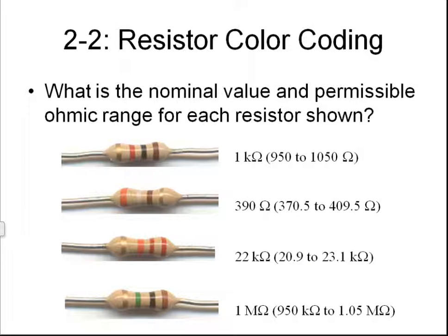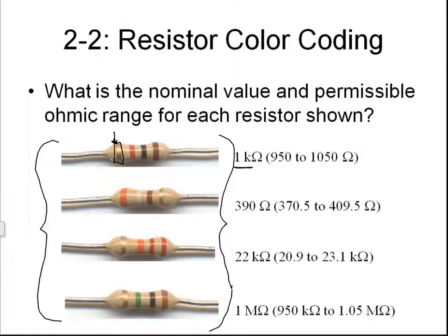All right, and here's another set of color code ranges. By the way, most of what I'm presenting here can be found in your Lesson 1 Chapter 2 PowerPoint slides, so download them and go ahead and review them. And you can see 1K ohms with a 20% band. You notice you don't start at the gold or silver band when you're looking at the value.